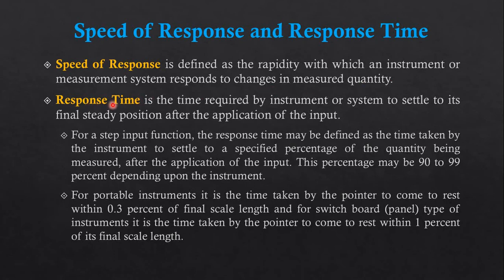Now, response time is the time required by an instrument or system to settle to its final steady state position after the application of the input. Whatever type of input we are applying to our instrumentation system, it requires some time to stabilize that value. Suppose we are going to measure the speed of our bike. If we are increasing the speed of the bike very rapidly, at that time what's going to happen?